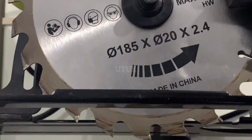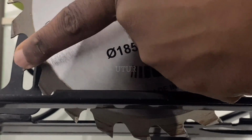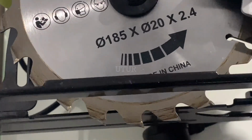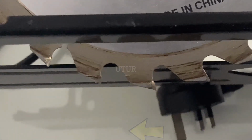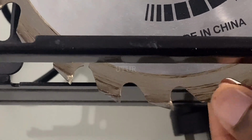So, I would be using it to get the job done, but not overly extensively, as I do not want to compromise on the integrity of the blade. I would try as much as possible to keep my hands steady, whilst cutting strips off of the hard plywood. And I will also be adding 3 mil to the depth of my cut so that the blade can cut through the hardwood plywood material at the base here.